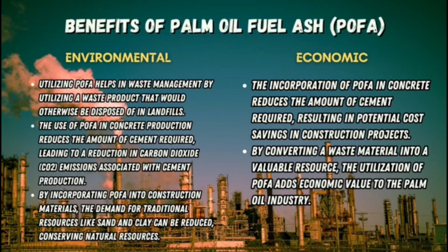So here we can see that if we use POFA in construction, we can reduce the amount of palm waste being disposed of in landfill. Next, the use of POFA in concrete production reduces the amount of cement required, which leads to a reduction in carbon dioxide emission. As we know, cement production produces a lot of carbon dioxide emission.